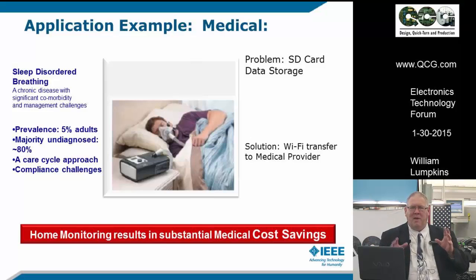The problem is the designer didn't really think about the fact that an SD card has only so many reads and writes before it starts to fail. So what starts to happen is after you start hitting the max amount of read and writes on that SD card, the machine no longer is able to read the data parameter, and so the machine would start to fail. It would fail way before its manufacturer warranty says it should have been failing. And the simple fix is, okay, you got to reprogram that SD card and stick it in there.